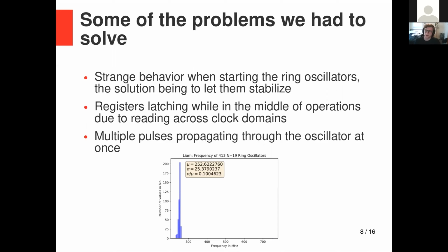So essentially we just worked our way around that problem by directly reading the counter, so directly making a counter circuit that increments a value in memory as the ring oscillator goes around. And then we just read that value off by the clock and hope it doesn't collide, essentially. We experimented with some things. You could disable the ring oscillators. I believe in the latest version, we stop the ring oscillator, then read it, to prevent that sort of collision. Because if it's trying to write to memory when we're reading from it, then we get garbage.